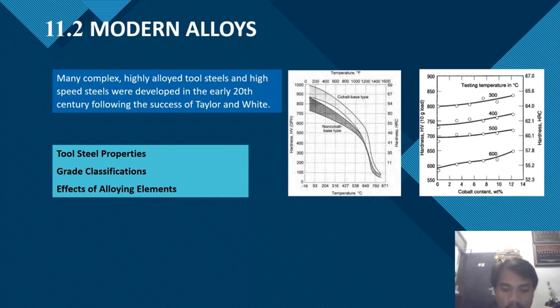Red hardness, also referred to as hot hardness, is the capability to retain hardness at elevated temperature. And toughness is the ability to resist breakage, chipping, or cracking under impact loading. Toughness may be viewed as the opposite of breakage. And wear resistance is the ability to resist the effect of abrasion and erosion normally encountered by contact and interaction with outside sources.